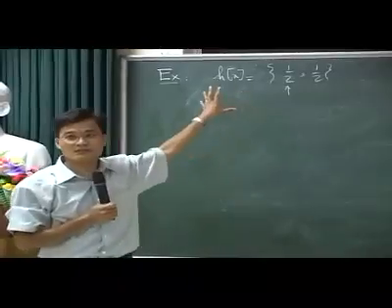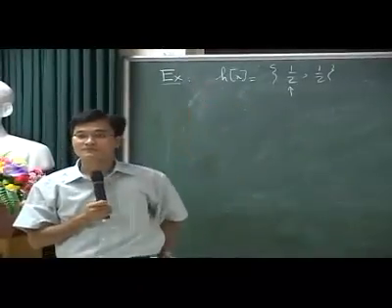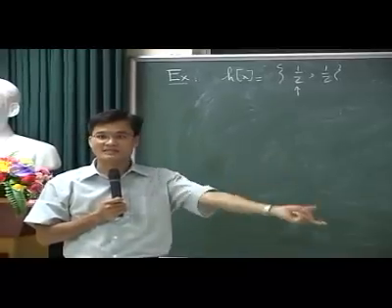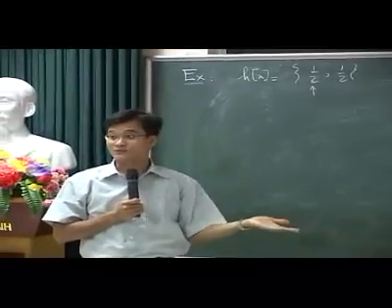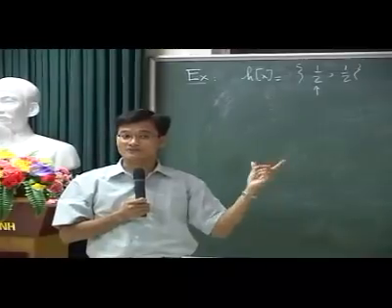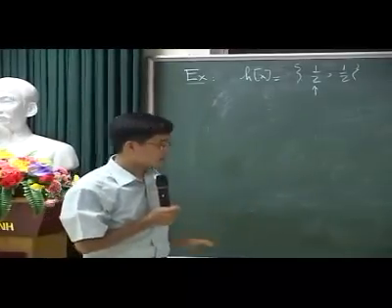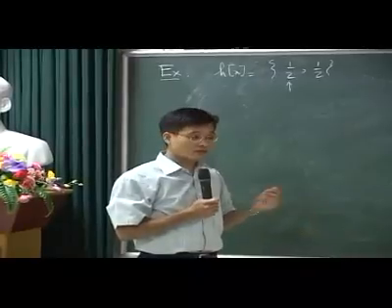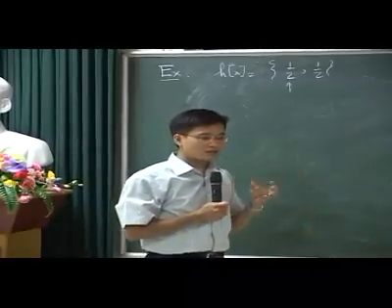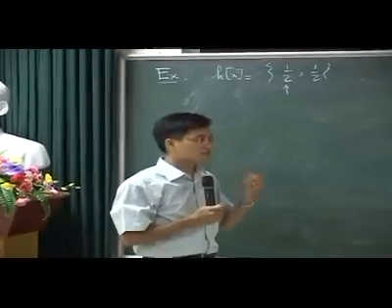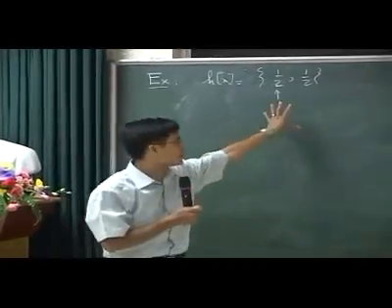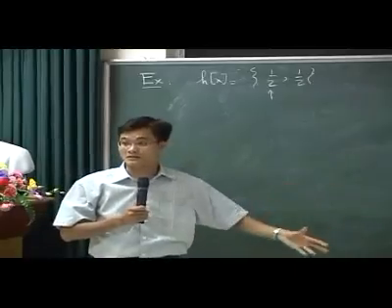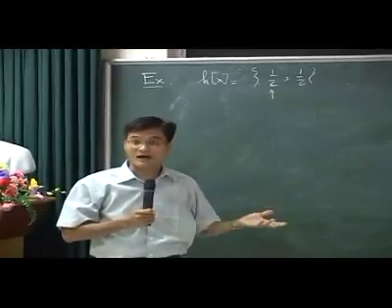I filter a signal with that filter. Just take the sample x[n] plus x[n minus 1] and divide by 2. Right? Just taking the average. Let's see what this filter is doing to our signal. Intuitively, early on we see that doing this average, you can do more, but I just put 2 here, seems to have an effect of smoothing out the signal. But now we want to see really why.